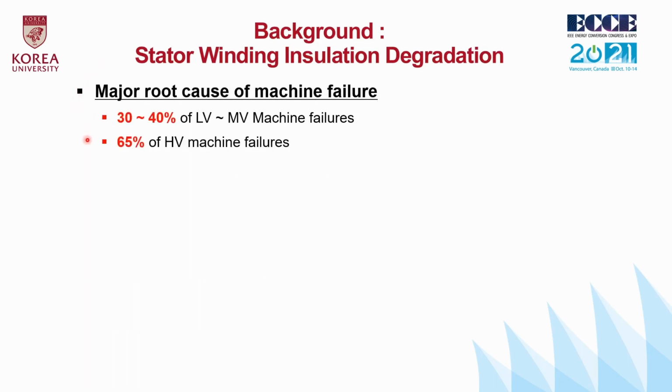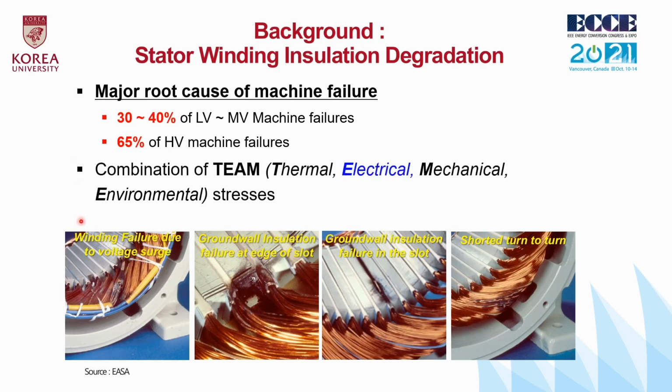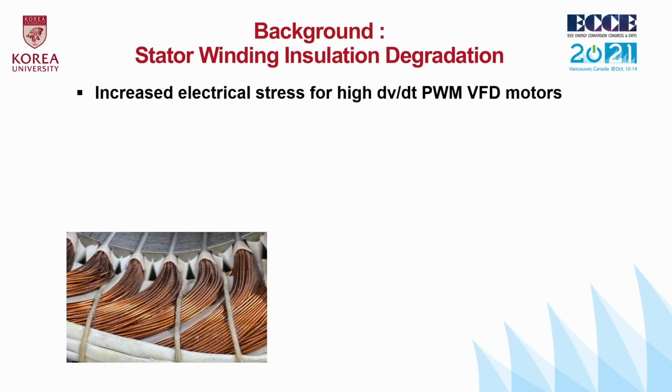The stator winding insulation failure is one of the major failure mechanisms of electric machines. The thermal, electrical, mechanical, and environmental stresses could degrade the machine insulation. As the number of motors operated with inverters increases, the high dV/dt voltage introduces additional thermal and electrical operating stresses.